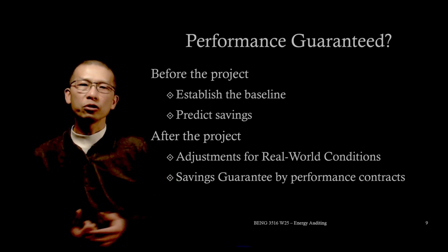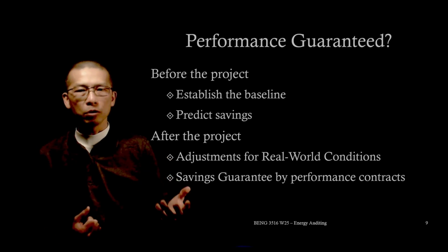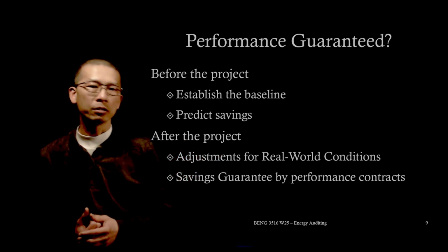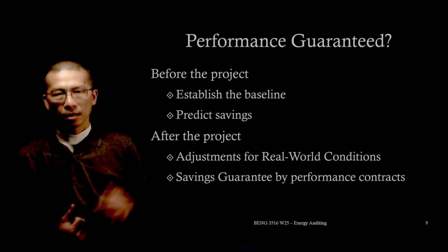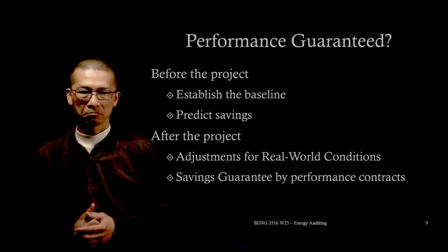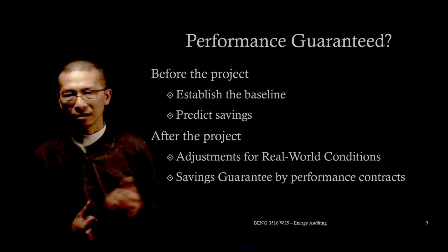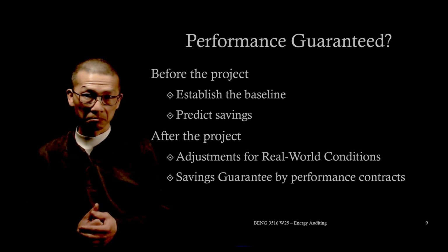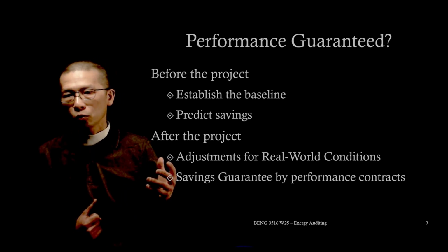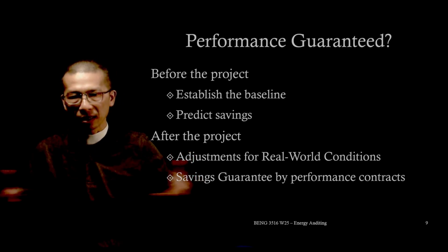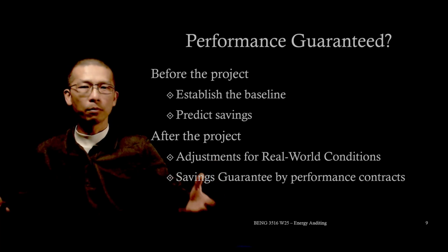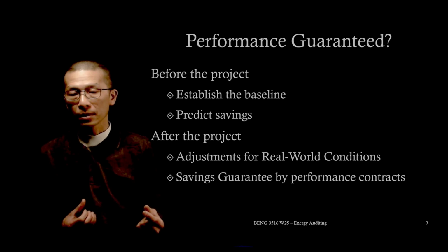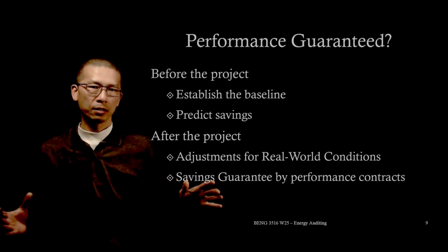Also, operational conditions: equipment runtime, occupancy level, and weather conditions. And system performance, like HVAC load, lighting levels, and motor efficiencies. The goal is to create a baseline energy consumption model that can represent how much energy would have been used if no project was implemented.